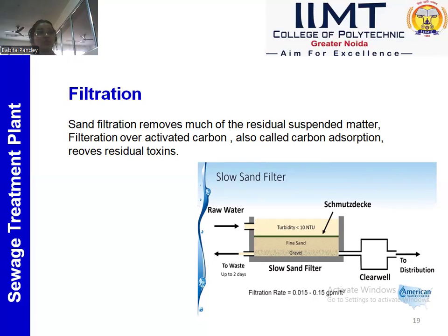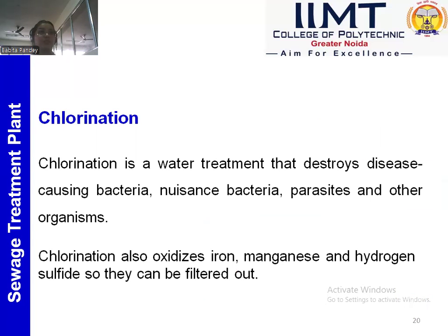Here we have the slow sand filter and the rapid sand filter. Slow sand filter, as compared to rapid sand filter, requires less maintenance. It is cost effective, but it is not easy to use. It is very time consuming. According to the required time and feasibility, we use the type of filter we need.